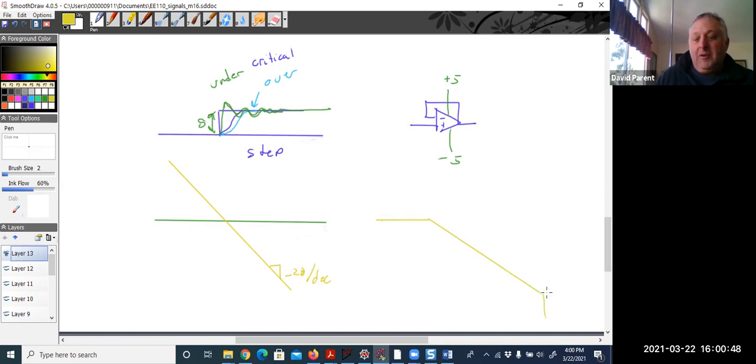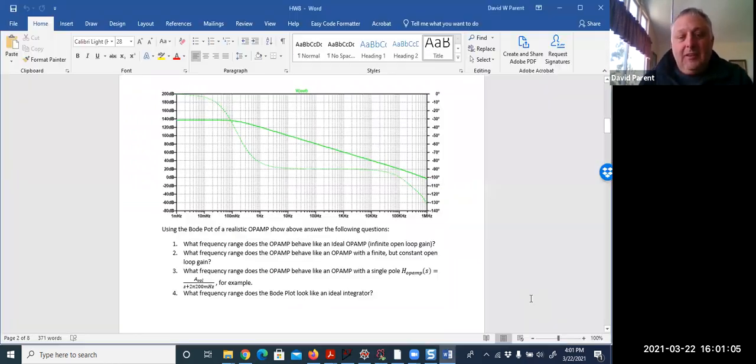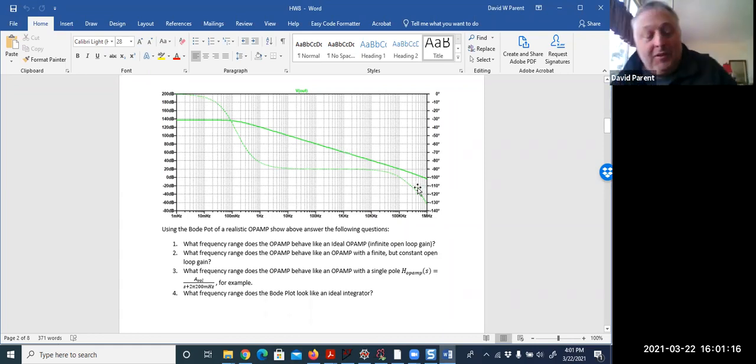If you see another break, well, it's no longer acting like a first order filter. What I'm trying to say is between here and here, it's acting like a first order. Then when you see that other break, oh, now it's acting like a second order. Because if I zoomed in and only showed you 1 millihertz to 1 kilohertz, you'd have no idea that this was happening. It would look like a first order to you, all right?